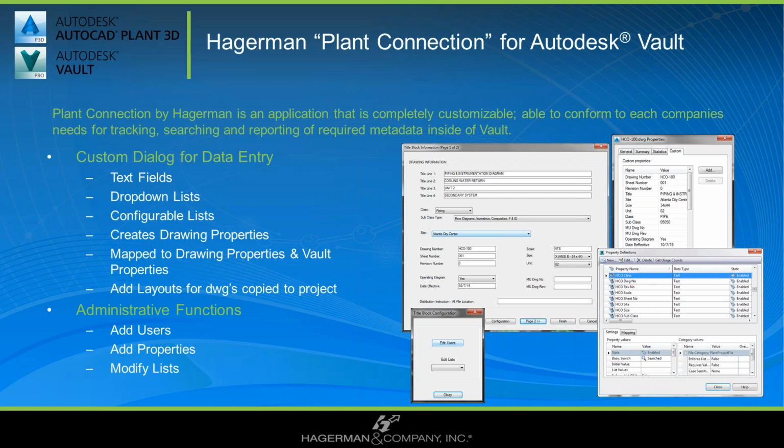And for those of you that know or have looked into it, Plant and P&ID use 3 databases when Vault is involved. You have the plant P&ID master database, you have the Vault database, and then you have the local workspace database, and that's an SQLite based. The other two are SQL based, but they are 3 separate databases.